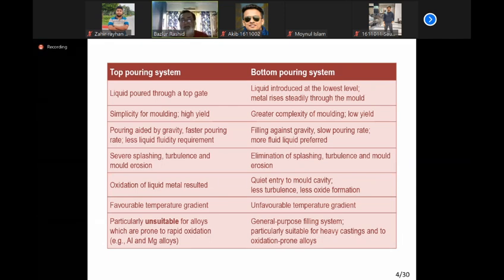On the other hand, if we pour from the bottom, the first liquid is going up and the last liquid is at the bottom. So the last liquid is hotter, but its density is less. The first liquid is colder, density high. So again, we are saying that the temperature gradient is not supposed to be this way. Hotter liquid should be on the top, colder liquid should be on the bottom.